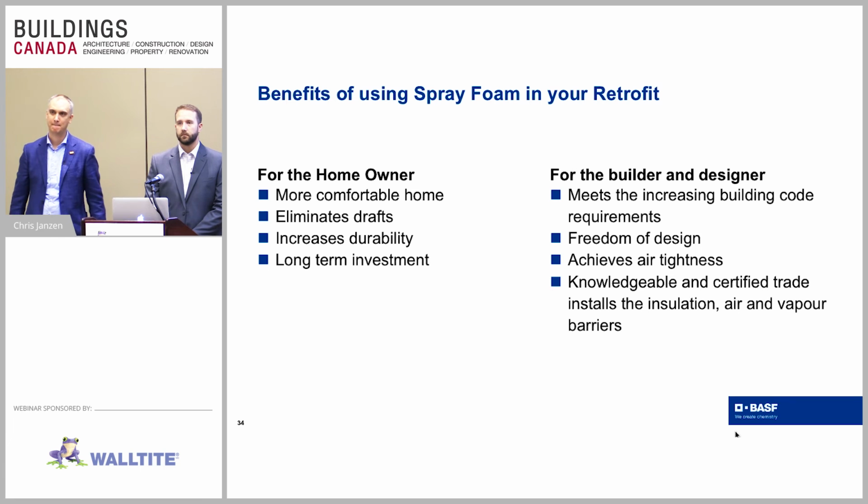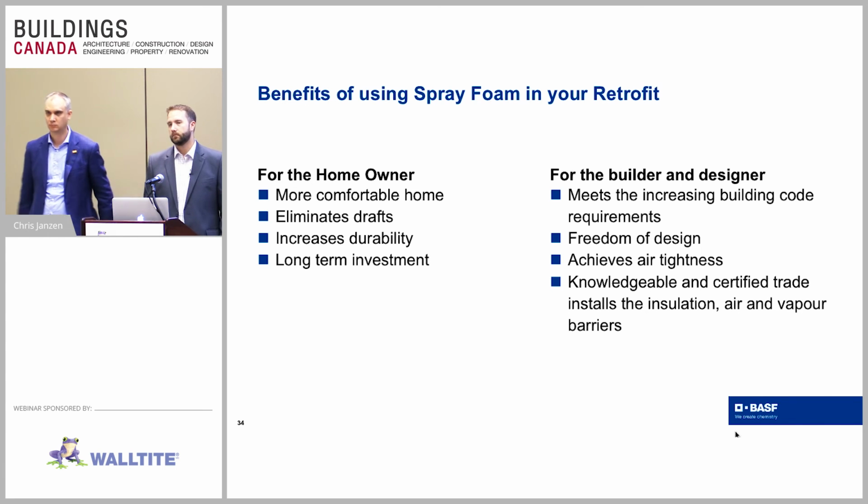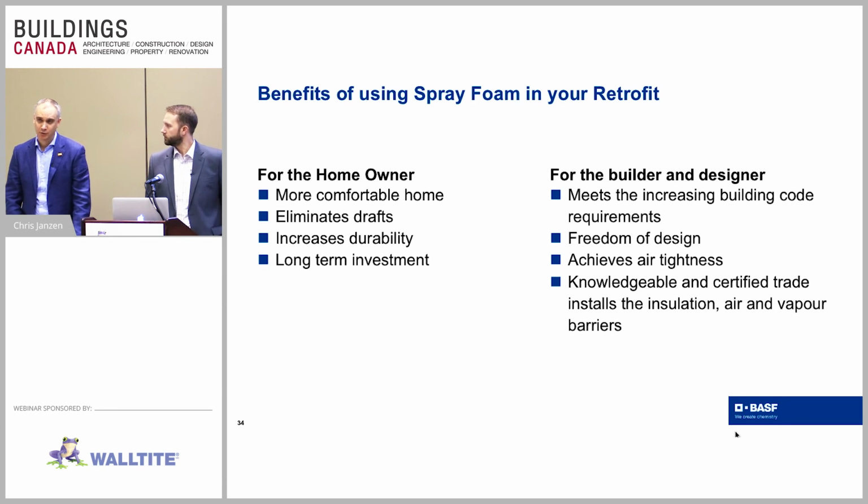Are you aware of which OBC provision in our code recognizes the role of the spray foam as obviating the need for plywood because of its inherent racking strength? The OBC itself, the racking strength requirement is actually coming from the drywall.